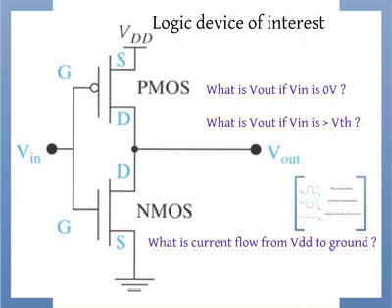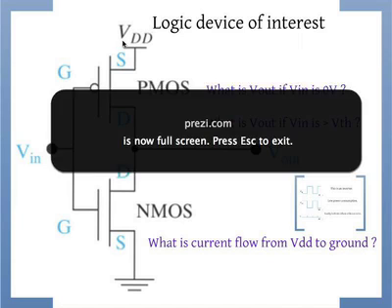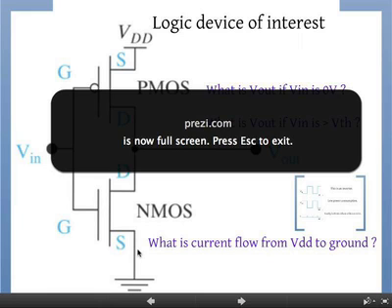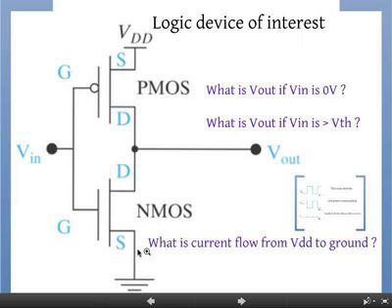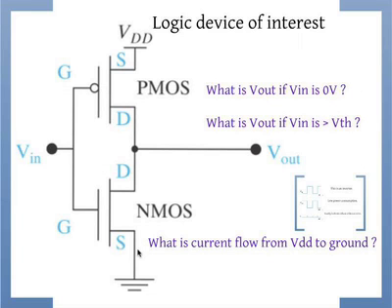The current from the battery, which is VDD, to the ground is basically 0, irrespective of how you use it. There's a small current that flows when it switches its state, as we know when we talked about switching in MOSFETs, capacitance and switching. Other than that, the current is pretty much 0, which means a low power device, which is why you can use billions of these. Okay, so this is a very beautiful design, very simple, and very important.